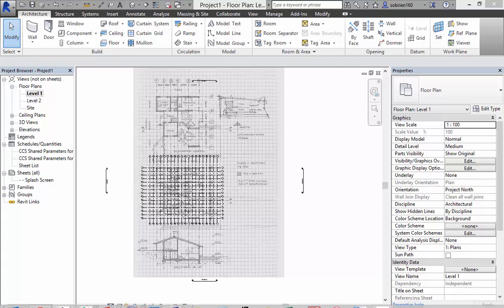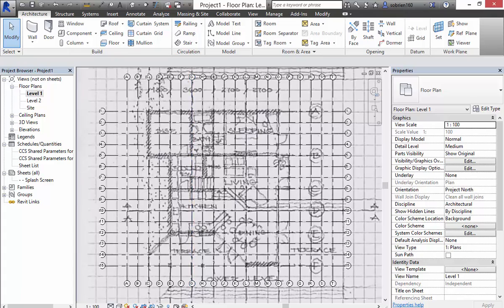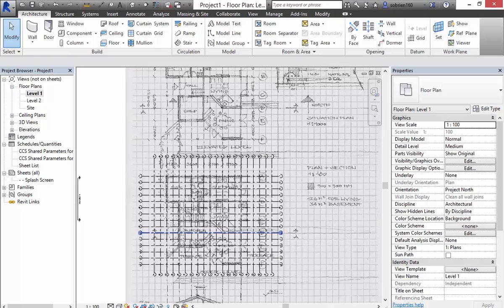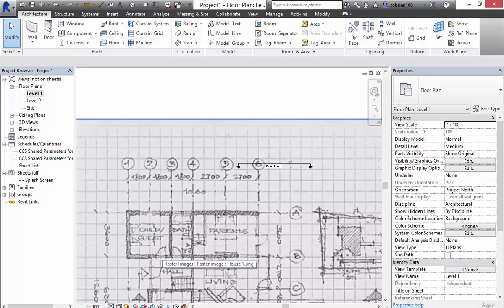Okay, guys, so most people have more or less got something going on. If you've got something like this, you have the initial module set up for the house. Now, a grid line like this is usually used where the main structural elements of the building are, but we want to use it as just a design element.